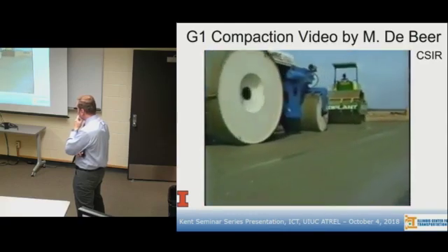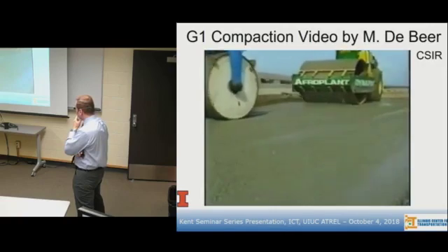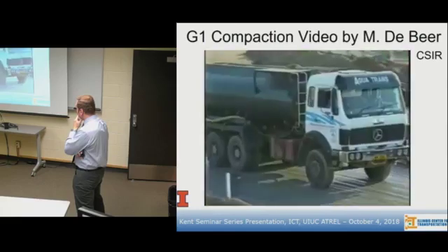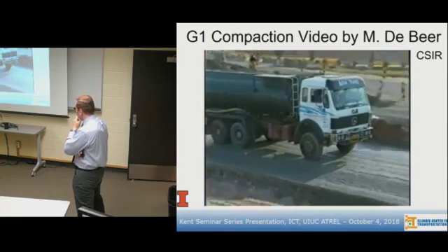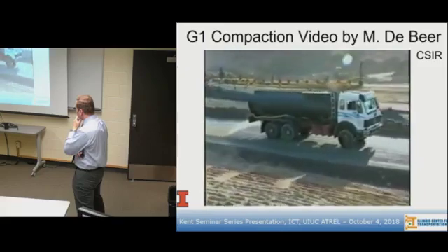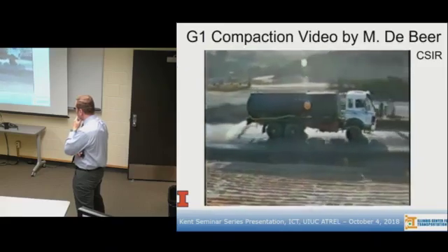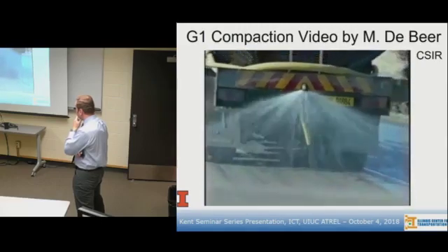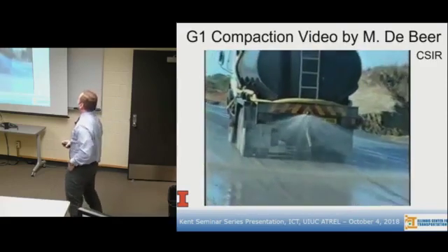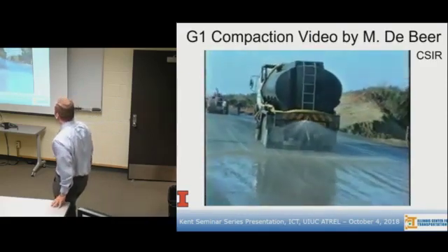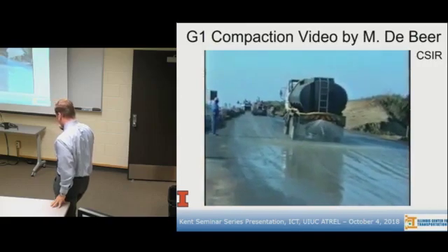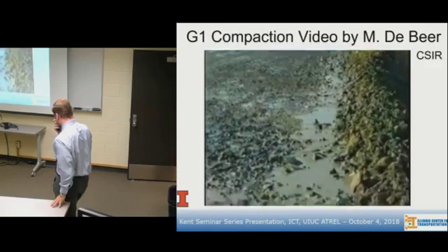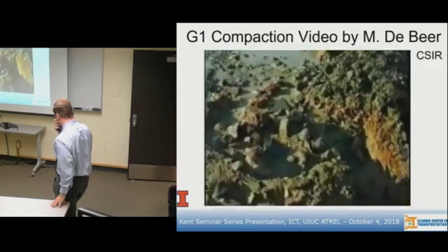The saturated fines also serve as lubricant in the process of reorienting and interlocking the larger aggregate particles. The layer must be saturated and slushed in relatively short sections of up to 200 meters, depending on equipment available on site. It is more effective to apply small amounts of water continuously than large amounts at longer intervals. It is advisable to apply the water to higher areas of the road and allow it to spread unaided to the lower areas. The shoulder should be breached to allow for the drainage of excess construction and slushing water.